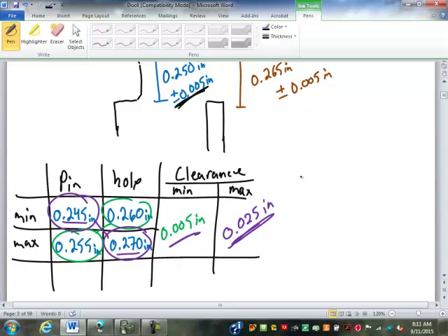And the more clearance there is, the more likely that nut is to come loose on the bolt in vibration. That's why when you look at military grade, by the way, you hear all the time, oh, the military spent like $800 on a bolt. And that's just it. The clearance, you could not hand tighten a nut on one of those bolts, period. You couldn't even hardly start a nut by hand on one of those bolts. The clearance between a nut and a bolt for most military grade stuff is less than 10 thousandths. Way less than 10 thousandths.